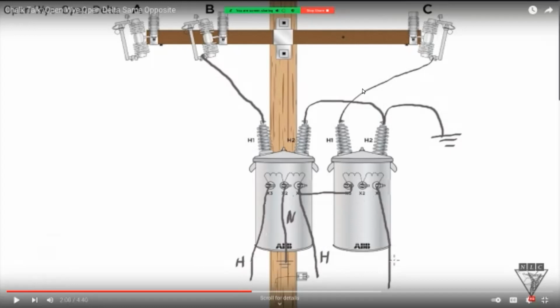In an open delta, everything that you see in the field, we're facing towards the two transformers themselves. The left transformer, write this down in your notes, is your lighting transformer, L-I-G-H-T-I-N-G, not lightning, lighting. And the transformer on the right-hand side, he calls a power transformer. Professor V calls it a power transformer also. I call it a high leg transformer.